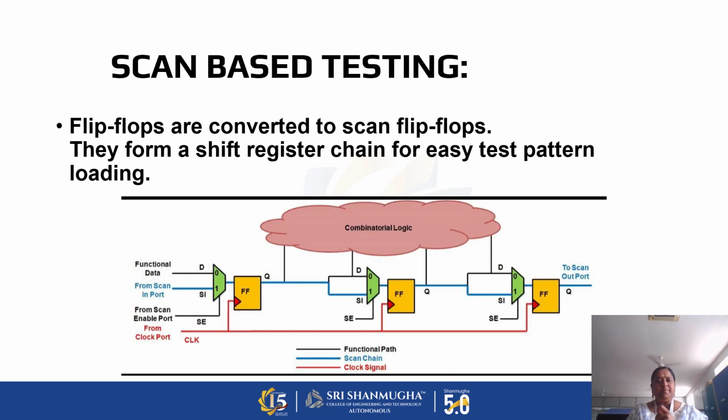Scan-based testing. Flip-flops are converted to scan flip-flops. They form a shift register chain for easy pattern loading. Here I have a combinational logic circuit, functional data, scan in input, scan enable port, and then I have a clock. So see here, scan-based testing is being performed in order to identify the faults.